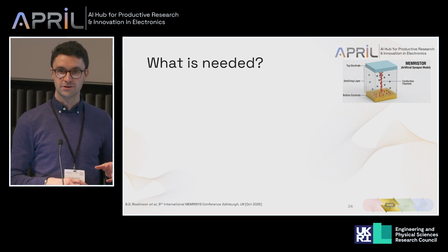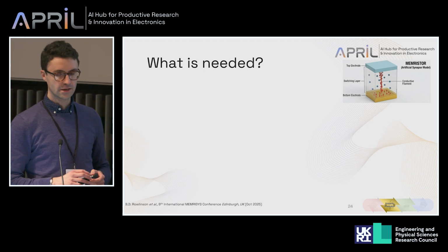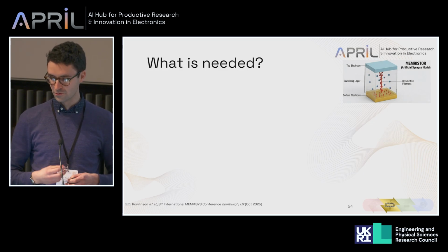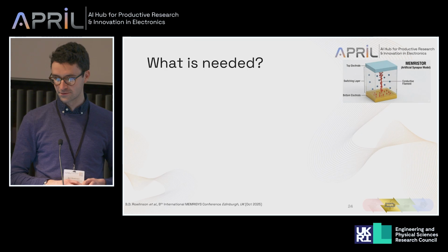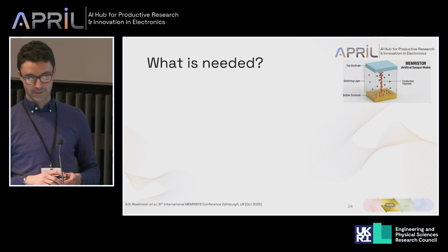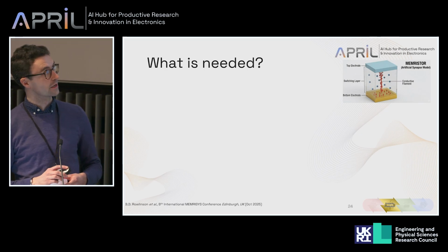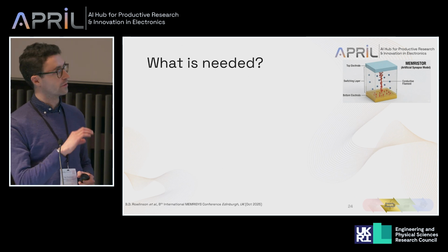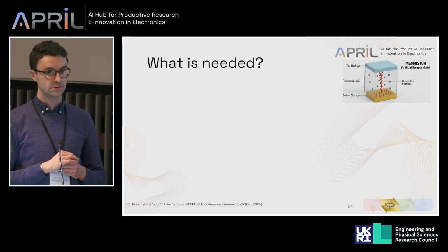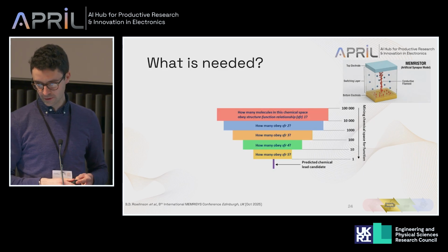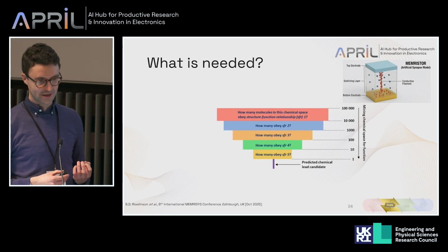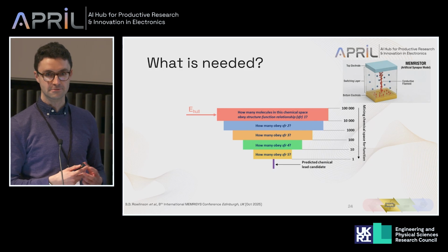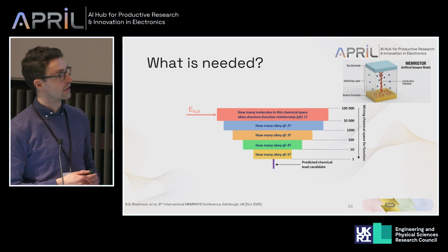and those are thin film transistors and memristors. So for the purposes of this talk, I won't touch too much on the memristor device itself, only to say that the resistive switching layer right in the middle there is very key to the operation. There are then two metal electrodes above and below. And what we're really interested in is understanding what the properties of this resistive switching layer are that are really key to how it performs.